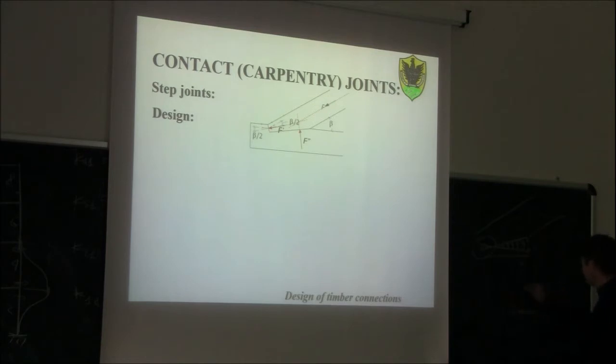So here's something like this. And you have here an axial force, then you have the self weight of the foundation, and you have a bending moment M. You compose all of them, you find that your resultant is here. What is the stress distribution underneath the foundation?